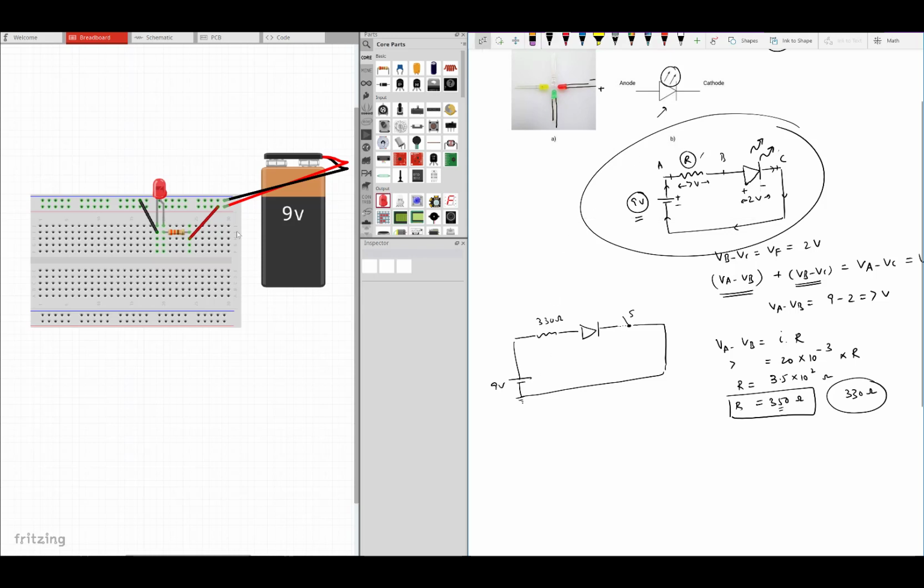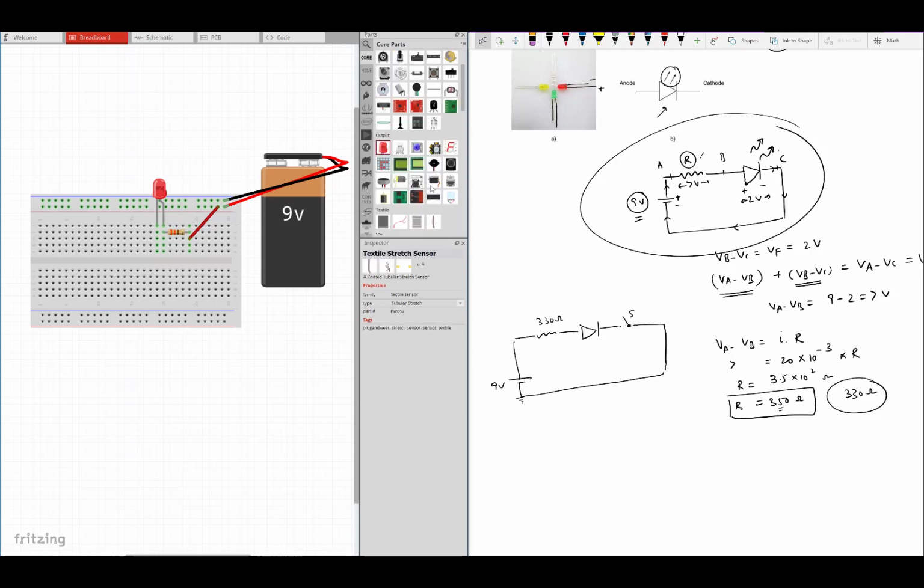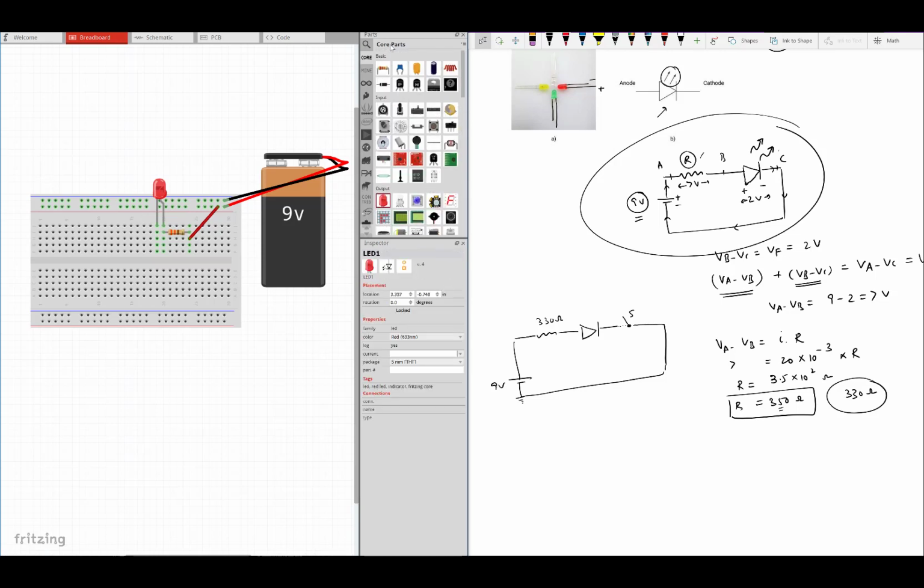So all I have to do now is basically move this wire from here. So I'm going to move this wire. Let me delete this, and I'll bring a switch over here. So let's find a switch. Scroll down, and if we can't find it readily, the easiest thing to do would be to do a search for switch. But here it is, the push button switch, right? What we call a momentary switch. So I'll bring it over here and I'll connect it in series with the LED.